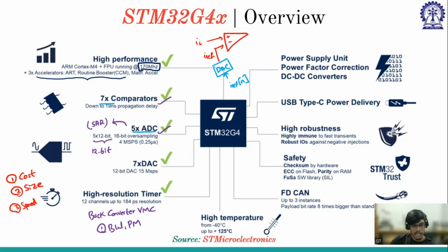Say the FPGA that we are using has a pipeline ADC, so it has lesser delay compared to SAR ADC, because SAR is serial and pipeline is a parallel ADC. So the delay will have an effect, and you have to see what speed of DAC they can go to, because we are specifically selecting an ADC and then making a board for the ADC. So it is again up to the user's choice.